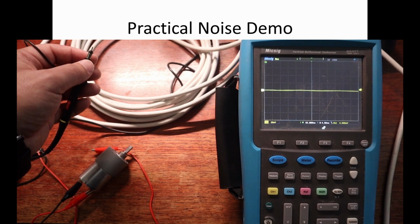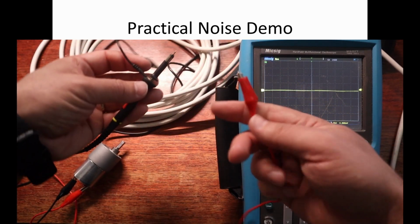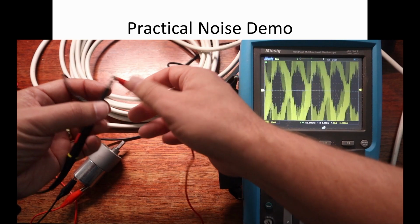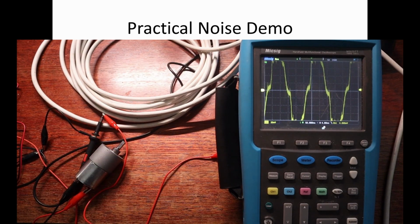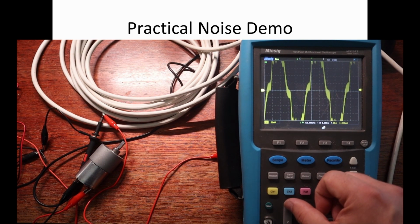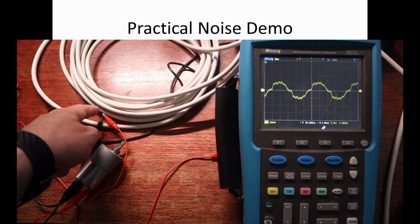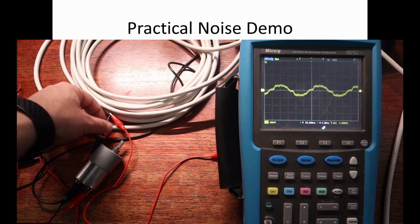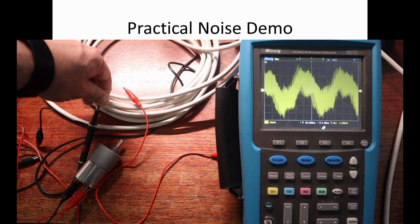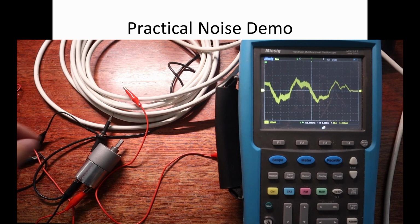Now let's look at a few other things that we can do, because that signal there is really pretty small. That's because these cables here are well shielded, but let's just connect a cable here, and this is just a short length of cable, and oh, look, the signal here we're getting is a lot larger. Peak to peak, it's about 100 or 200 millivolts from peak to peak. Now, if I touch it with my finger, so this piece of cable here is acting like an antenna. If I touch it with my finger and take this off, my body's acting a bit like an antenna as well and picking up electrical noise from the air. So we've got a whole lot being coupled in here.